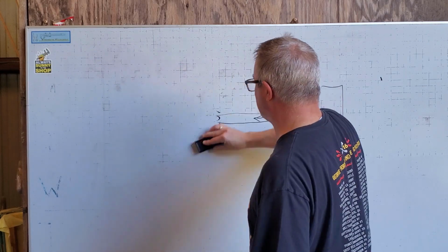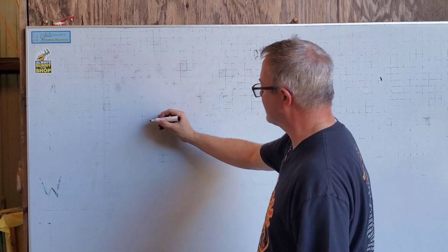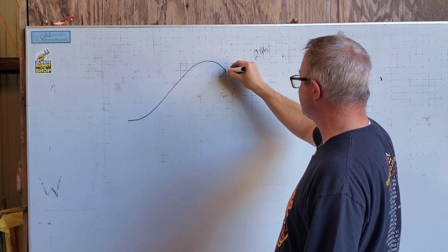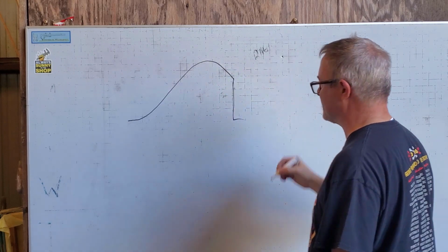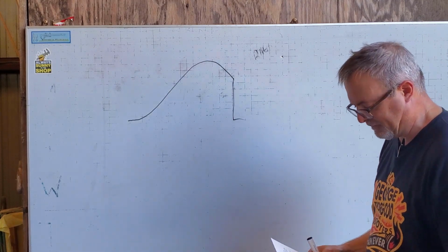So the torque as it applies to the crank is going to start at zero, build to a maximum, start to taper off basically, and then fall off a cliff when the exhaust port opens and dumps. And all of that will occur in 90-ish degrees.